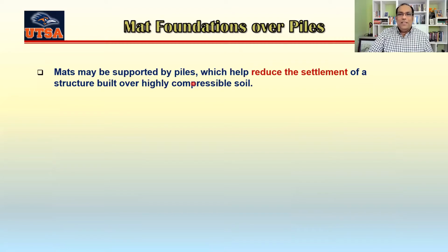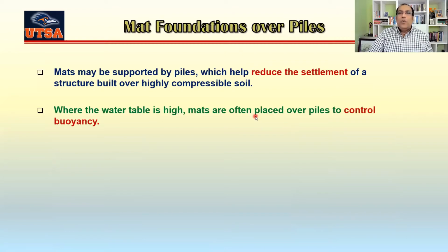There's a second reason for that, which is if you put your mat under the water, then there might be some buoyancy pressure that will try to push the building up. So in that situation, we also try to use piles so that the piles can hold it down. Okay.